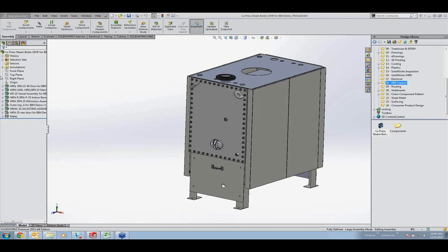In the past, we've always been able to split solid bodies, but now, using the split command and the sketch I have created here, I can split the surface body. Now I have 4 different surface bodies. Go ahead and find the one I want and isolate it here.